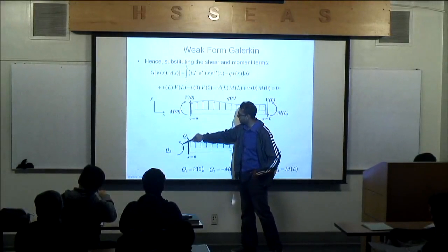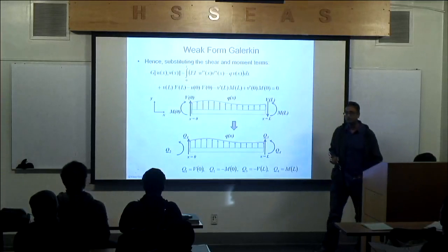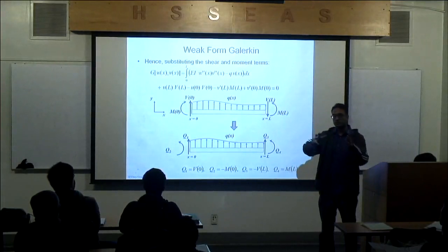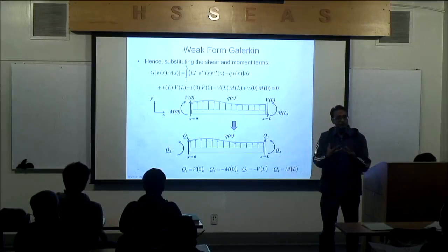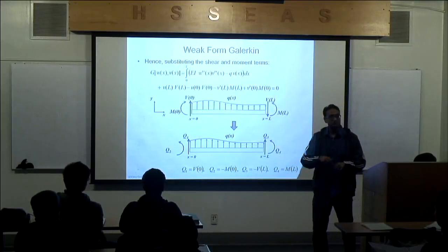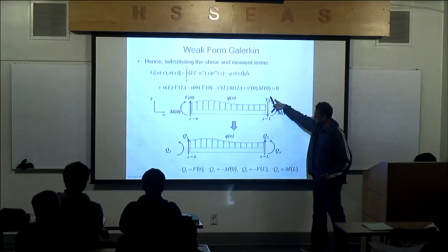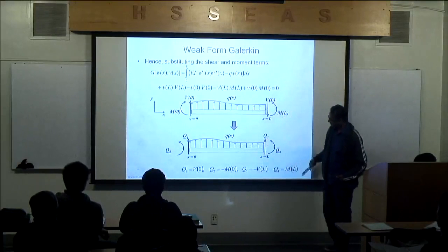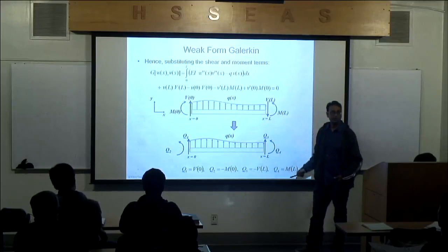So I'm going to define some new conventions. And the purpose of that is when later on I discuss finite elements of beams, if I want to assemble systems of equations or approximate solutions for every single piece in the domain, it would be very convenient if everything was defined in the same direction. You agree? Right? And for that reason, I want to make this VL the opposite. Okay? And so here you can see I created some minus signs here. And so these are going to just basically correct that so everything's in the same direction. Okay? That's the goal there.